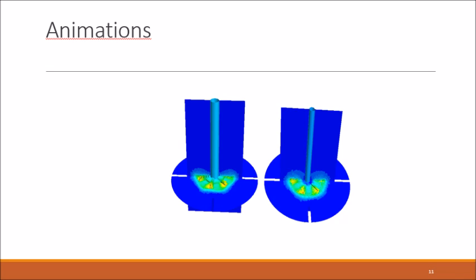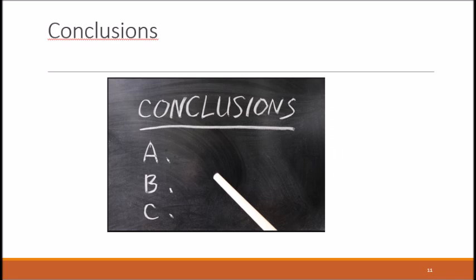Now, with respect to the velocity and flow profile, we can observe in this figure that these profiles are very similar between each other. The only difference lies in the fact that the shape of the region with higher velocity is different. In the case of the design impeller, it has a strange geometry where in between the blades the high velocity liquid is less radially spread.